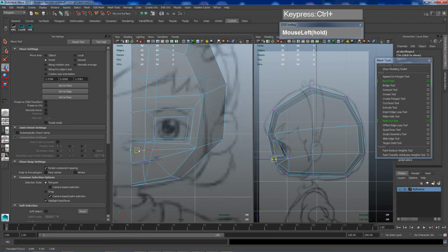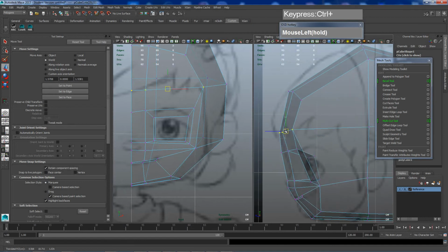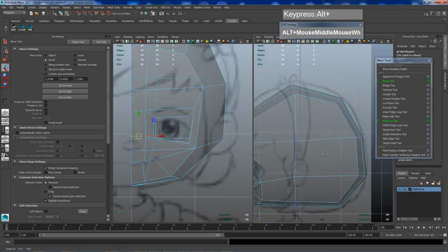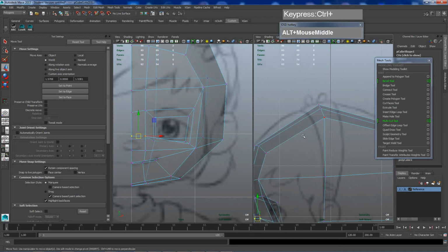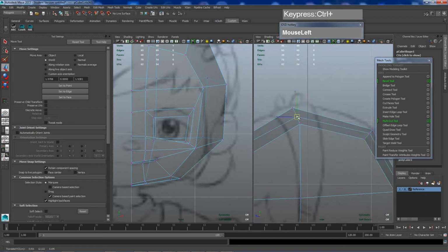Sort of spread them out a bit. So I'm going to pull this face down a little bit. Pull this up the forehead to make it rounder. So remember this: every time you insert an edge loop, move the vertices. Don't leave them sitting there.